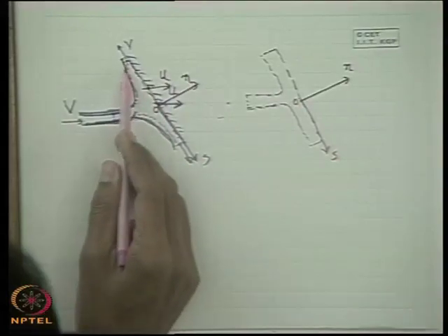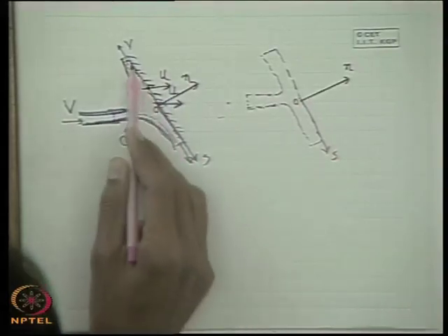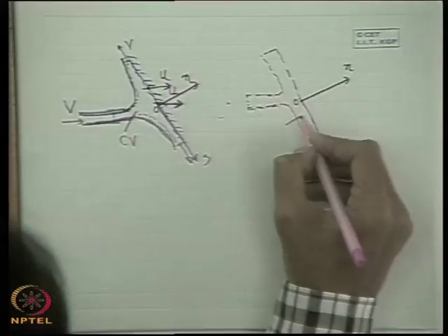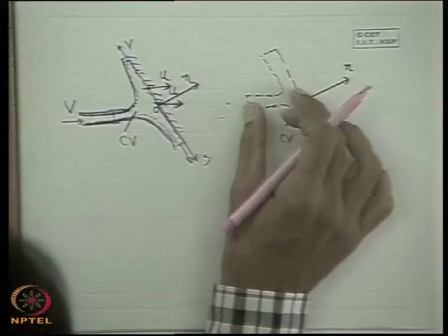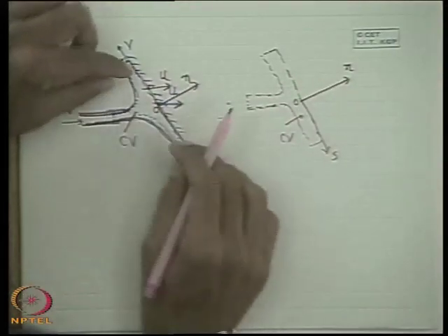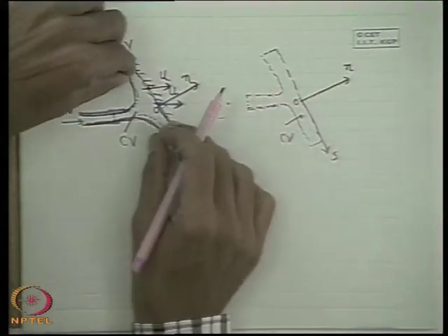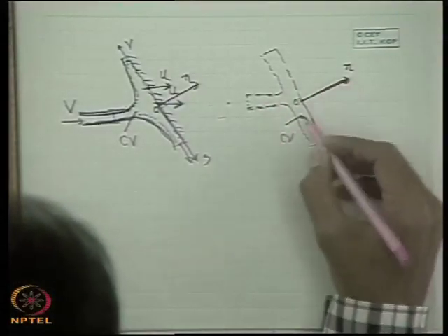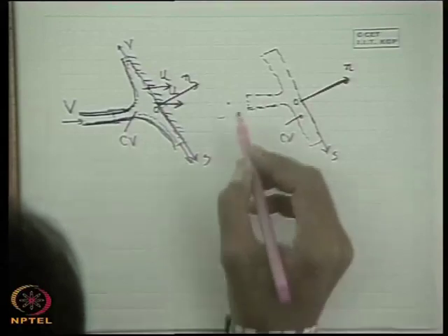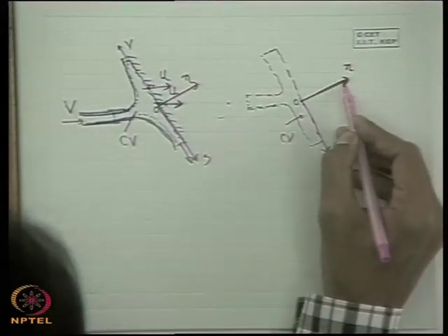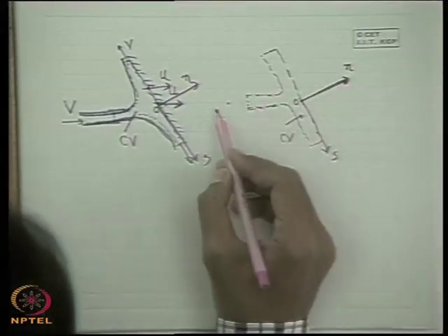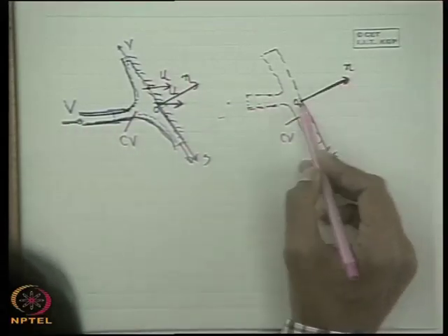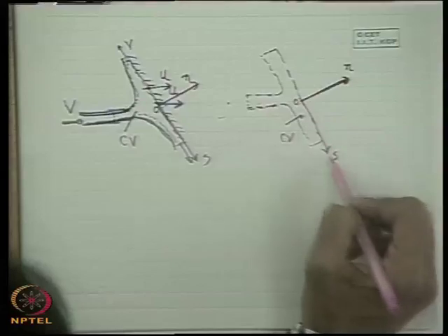In other words, through my control volume picture, I can say that this control volume is also moving with the plate. When the plate moves the control volume is also moving. Now, if we attach the coordinate axis to the control volume, the axes are moving, which means any analysis with respect to this axis will be done provided the velocity parameters are made relative to the axis, because the analysis will be made with respect to the axis.